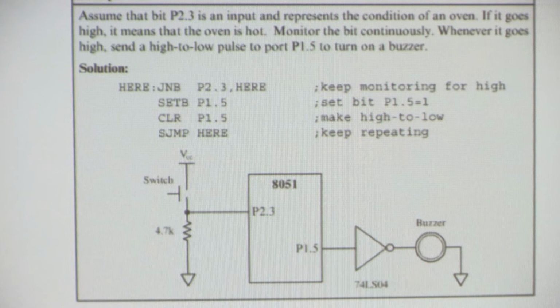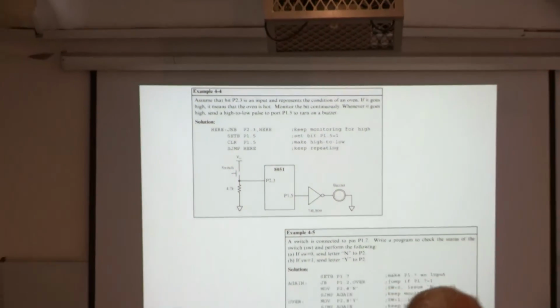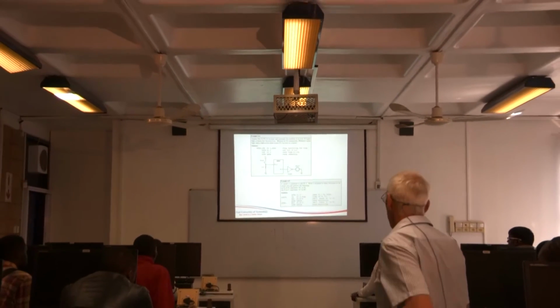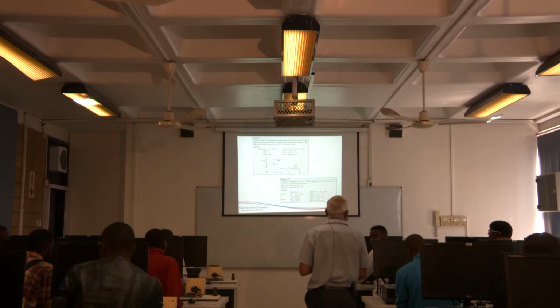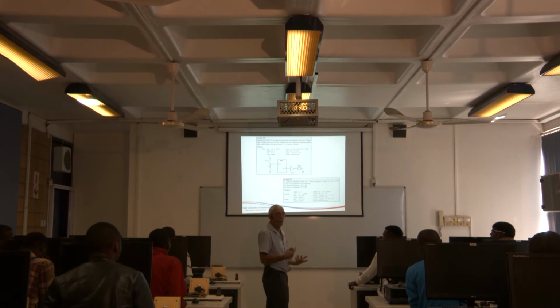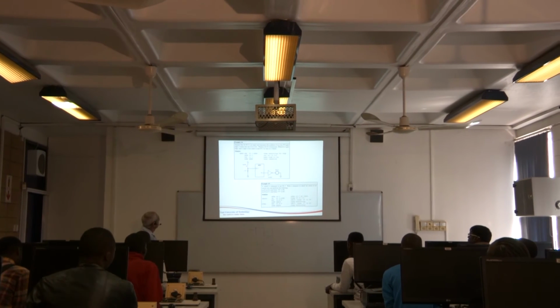Then all of a sudden it goes to a 1, because this can be a thermal switch, because we said it's checking the temperature. Now you know from your instrumentation side, you can have a thermocouple or whatever that's monitoring that, and at a certain level you're going to get a 1 out. Or you can have a bimetal switch, but as soon as there's a lot of heat, at a certain point it's going to bend and make contact. Now that's where your process instrumentation and electronics all kick in. Right? You can't be without that. So then that switch will close.